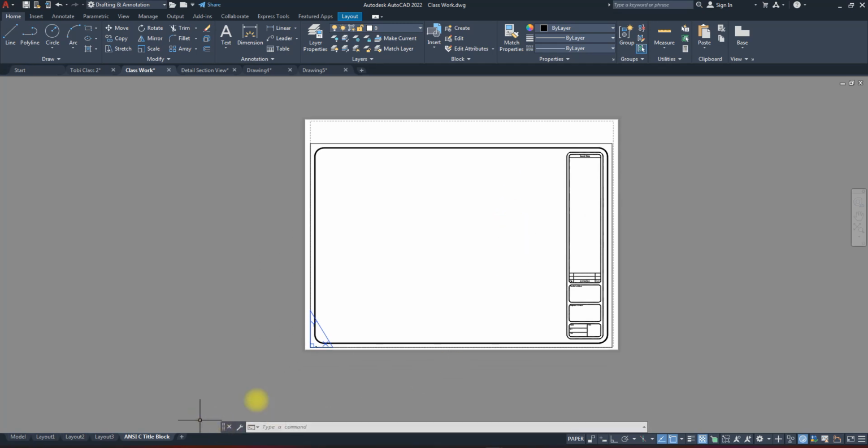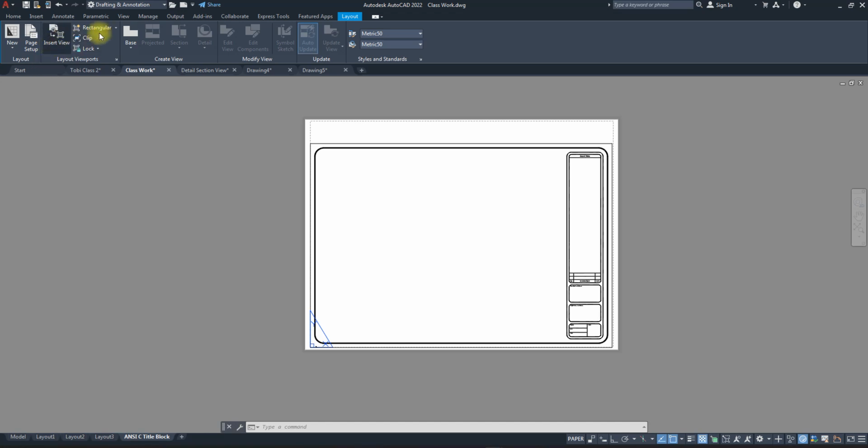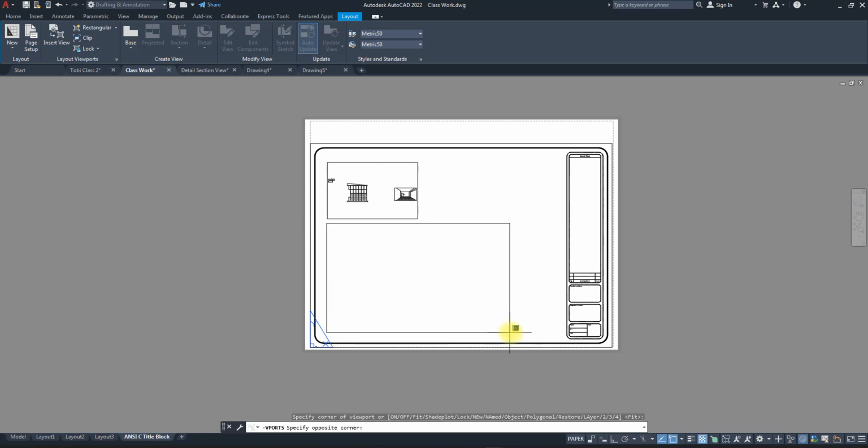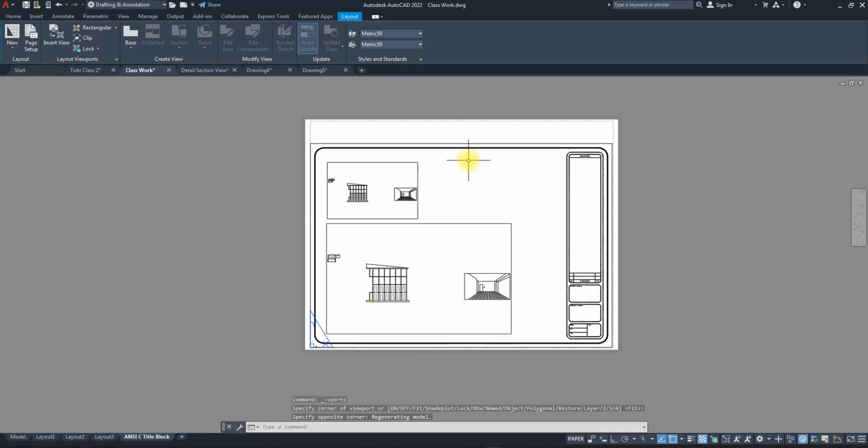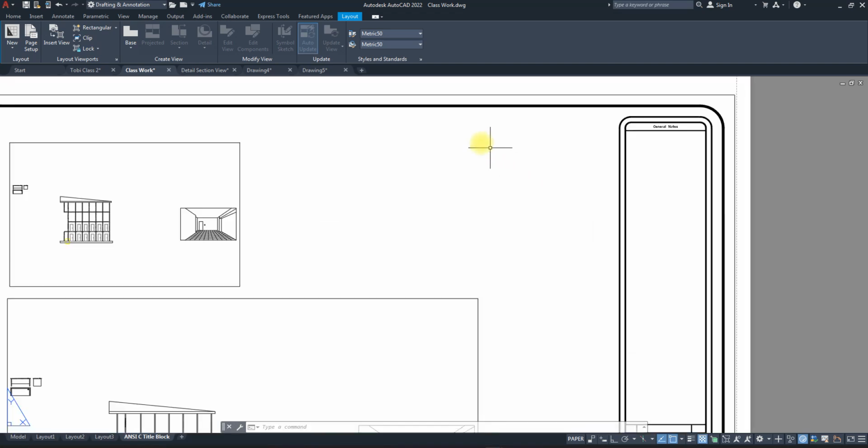But now, anytime you use from template, you don't get to have a viewport. So that means I have to go and add my own viewport. So that's okay, create a viewport here. So maybe I'll create a rectangular viewport somewhere here for the table. I want to have my table here. I want to create another rectangular viewport for, let's say here. So if I have a table, maybe a legend for whatever component I'm using, I can also put a table here, maybe use a viewport to show the table.